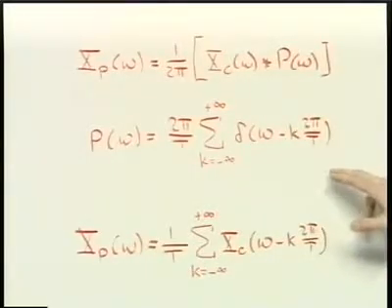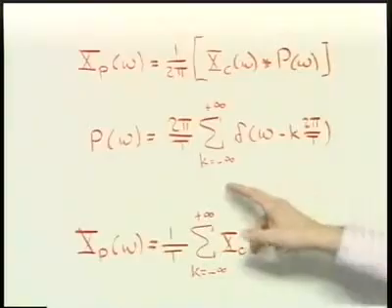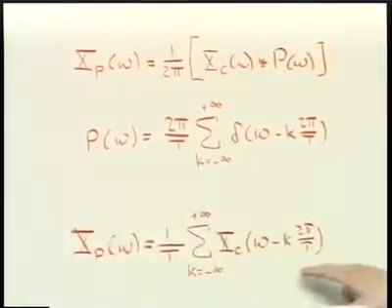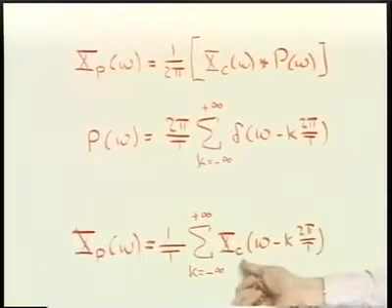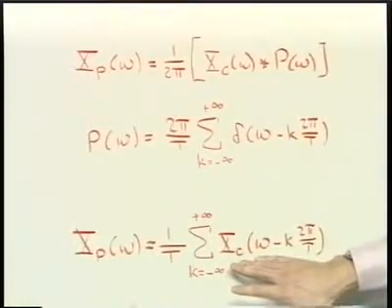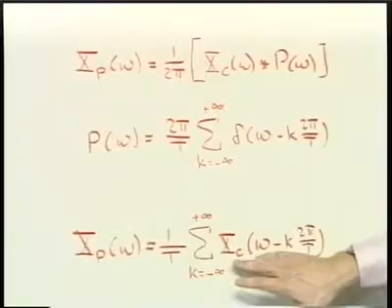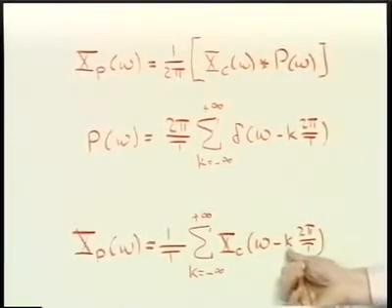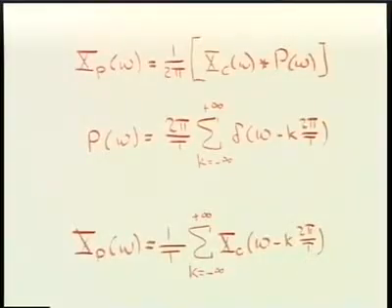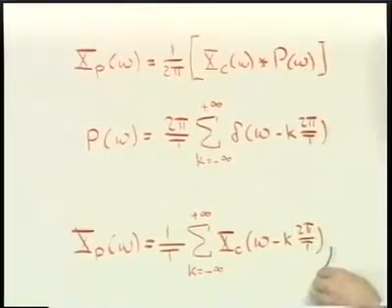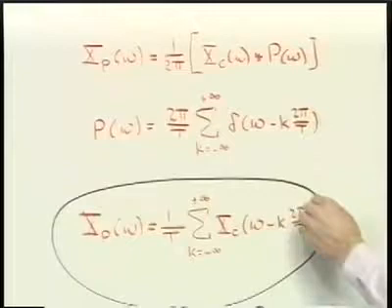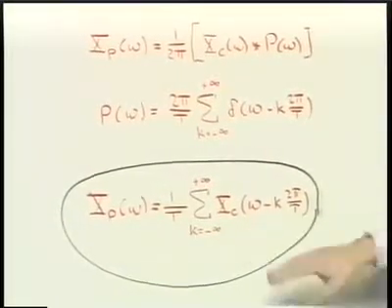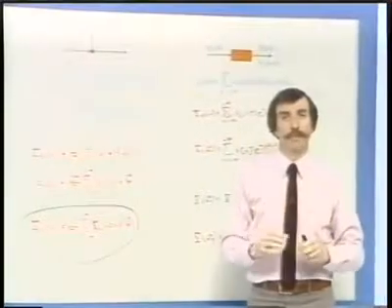Finally, what we end up with is a Fourier transform after the sampling process, which is the original Fourier transform of the continuous signal, added to itself, shifted by integer multiples of the sampling frequency. And so this is the basic equation that tells us in the frequency domain what happens through the first part of this two-step process.